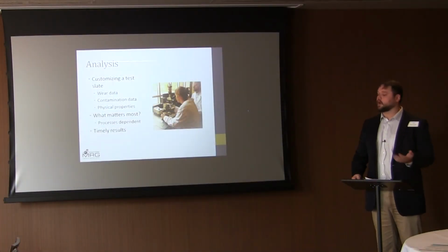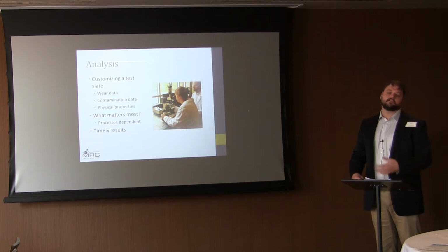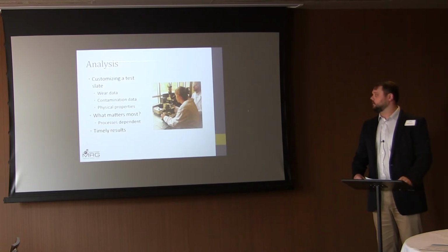And the other one in the lab is timely results. So when you get a sample, you don't want to let the sample sit on your desk for a long time. As it sits there, things can change. So the quicker the sample can get into the lab, and the faster the lab can analyze the sample, the better it is, because it's going to be most representative of that sample from when you took it.